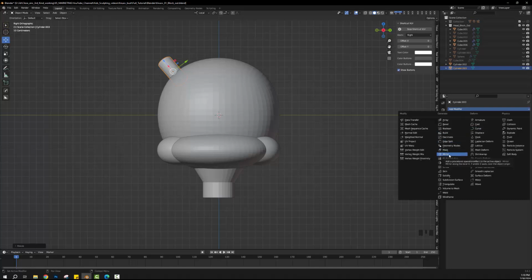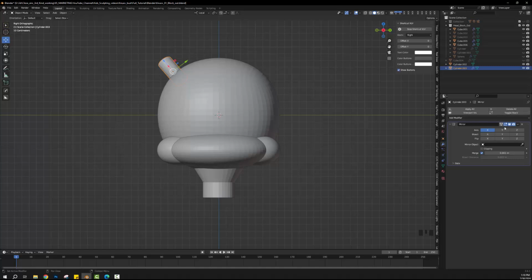And we're going to go again to mirror. And I think you know what we're going to do. We're going to go Y, unclick X, use the eyedropper to select, we want it to mirror it across the head. And boom, we get the exact same placement on the opposite side. Saved us a bunch of time. Love it. Okay. Probably a good time to save.